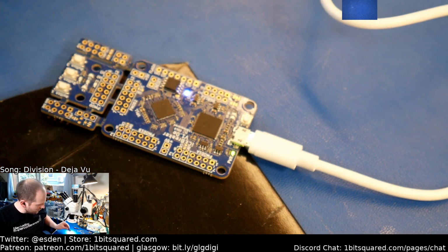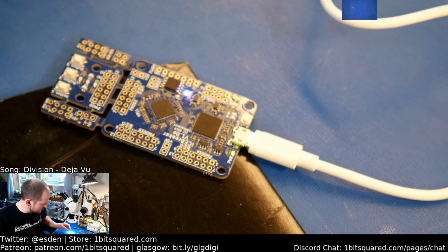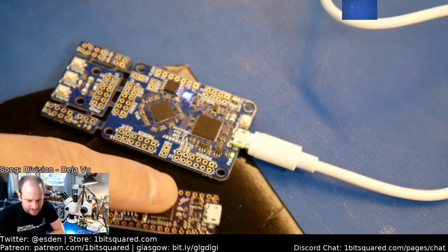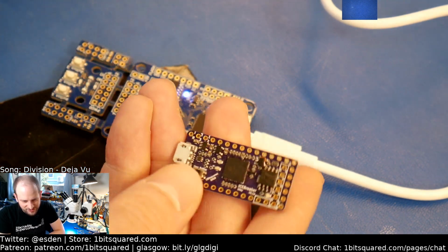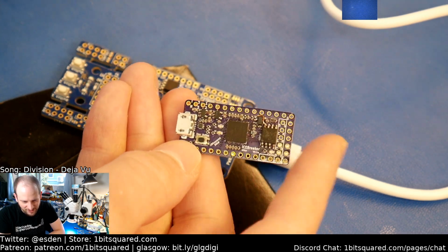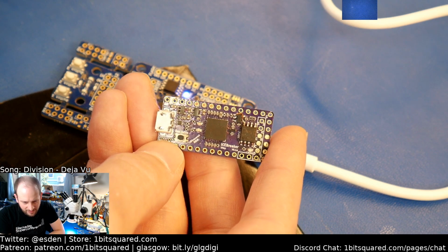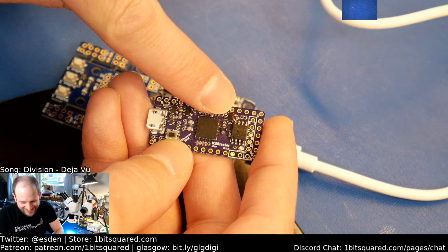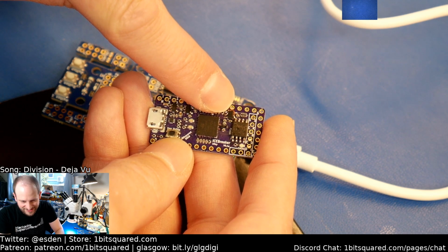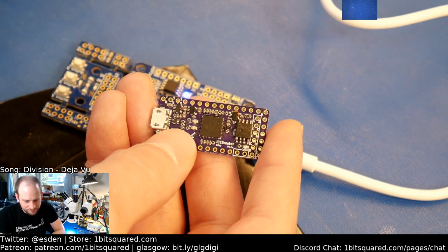And from that, I was thinking when I was making the iCEBreaker in 2018, that is already a while ago, that there should be also a smaller version of that. And this is the iCEBreaker-bitsy, or iCEBitsy. We should still probably talk about the name. iCEBitsy is not a bad name, I think. So this is the version A, and as you see, I made a little mistake here. So the crystal here, the footprint is upside down. So that is something I had to botch fix in this revision.